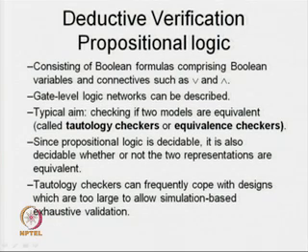In case of deductive verification, what we basically check is whether two models are equivalent or not. We call these tautology checkers, because in our design phase we have an abstraction. First we come up with a model, then we make it more refined, we go for another level. Every time we have to check whether we are going to get an equivalent translation or not. So, we can look for such an equivalence checker. Sometimes you can say tautology checker, or equivalence checker.